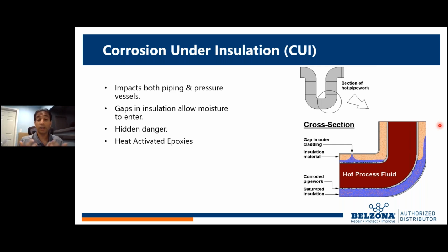The second part of it is conserving energy. The fact of the matter is, when you have hot process fluid, you can recover the energy out of that at a later time, and you could save a tremendous amount of cost. So that's why we insulate piping. It's safety, but it's also energy conservation. So it's necessary to do.